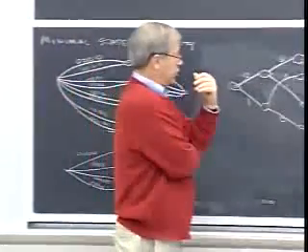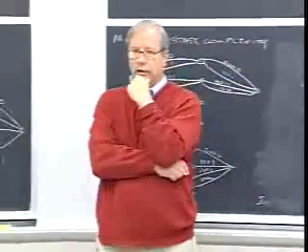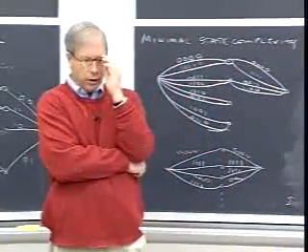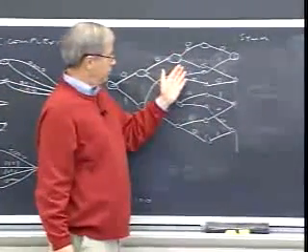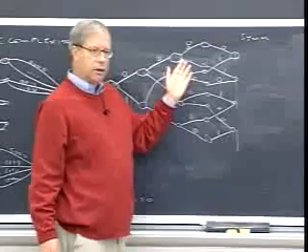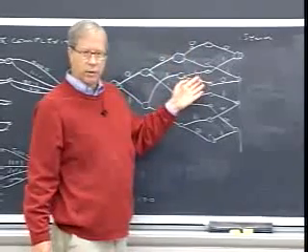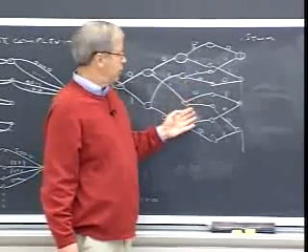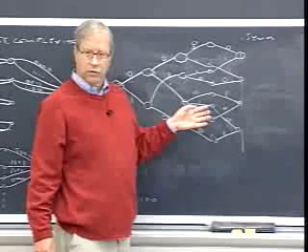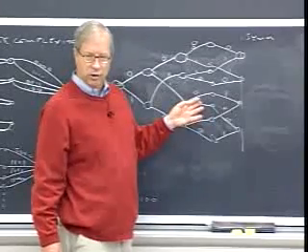And I will assert that this trellis is the minimal trellis in every respect, whether you're trying to minimize state complexity or, if you're using the Viterbi algorithm, really what you want to minimize is the number of branches, but there's a calculation about branch spaces in the notes that shows that this also achieves the minimal branch space size at every time, regardless of how you draw the trellis.